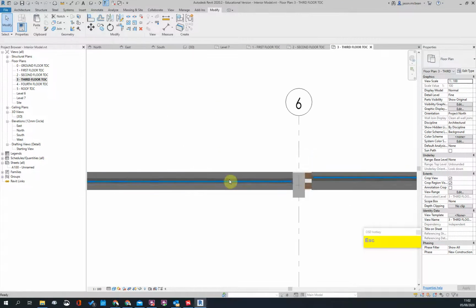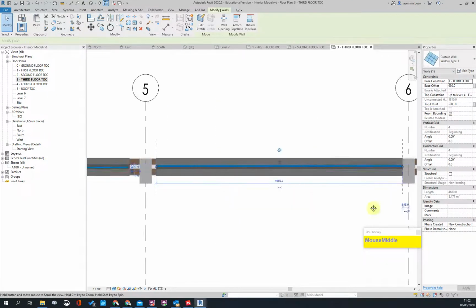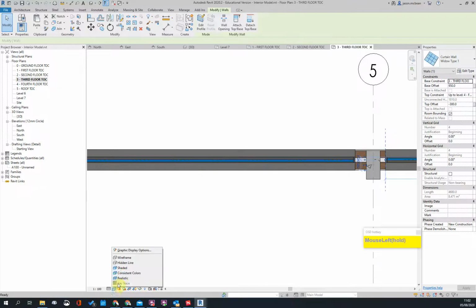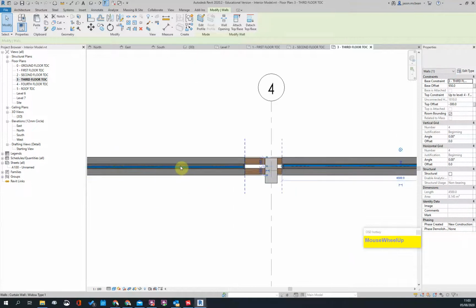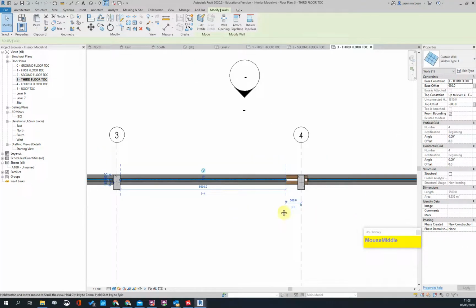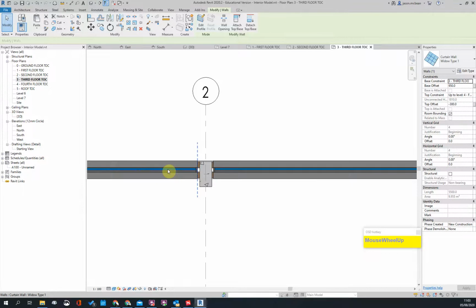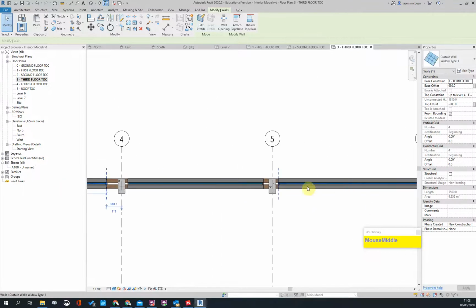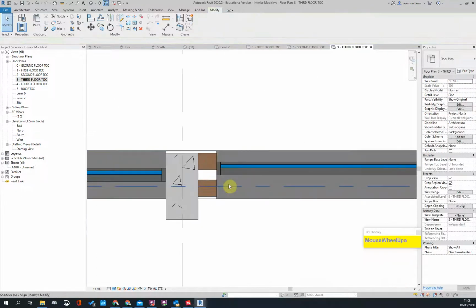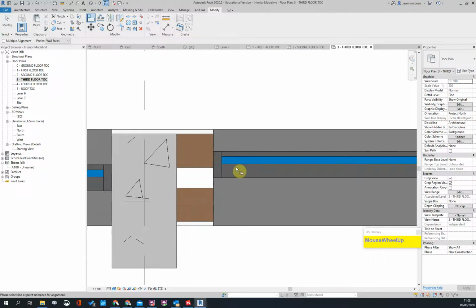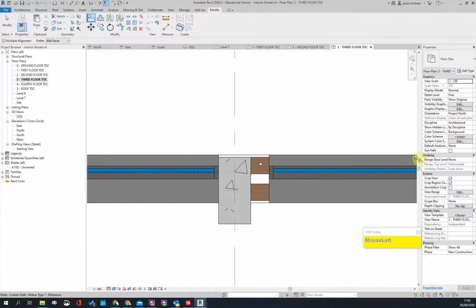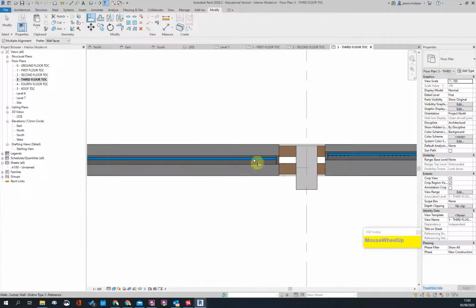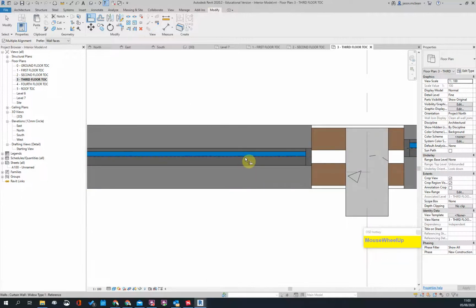Okay, then I just need to align. Oh, yeah, remember these always need to face exterior, external, shading with contrast. I think it improves the color a bit. Face exterior, face exterior. Generally, these windows line up with a work desk, like a workstation. Okay, so I'm going to use align. I'm going to select the center line of the curtain wall, embedded curtain wall. And I'm going to use multiple align. I'm going to select that one, so it'll keep aligning. It'll keep the command active. Okay, that one.